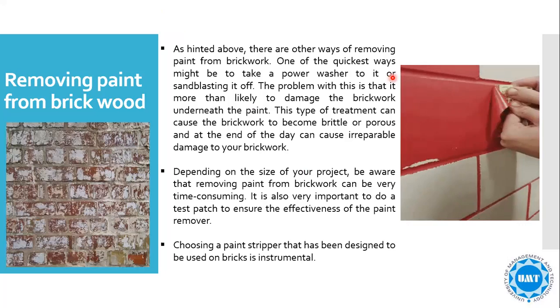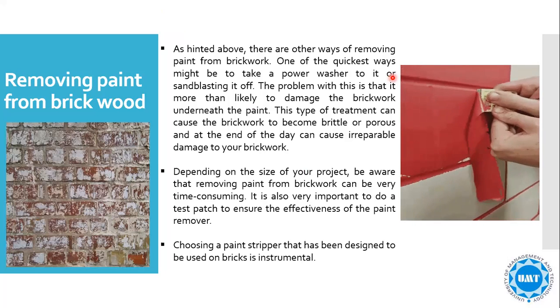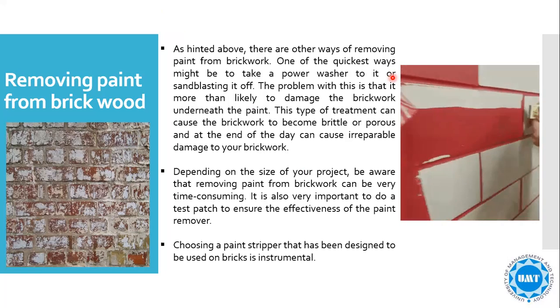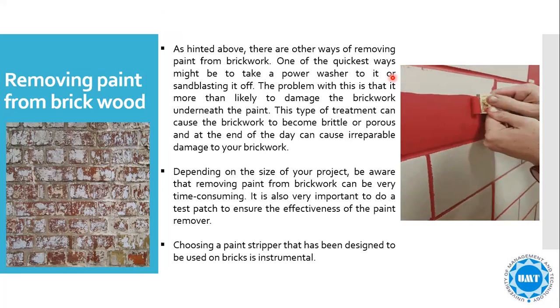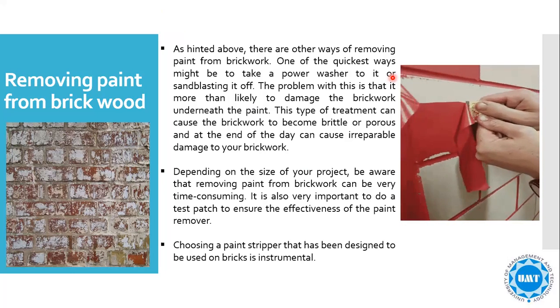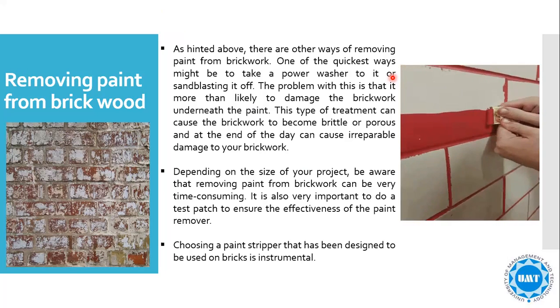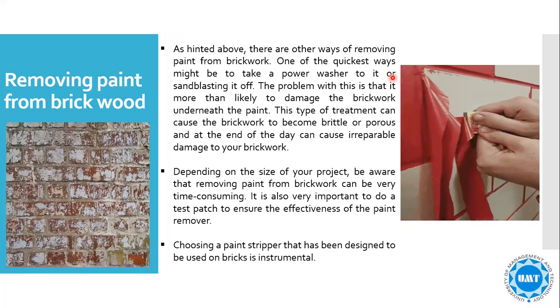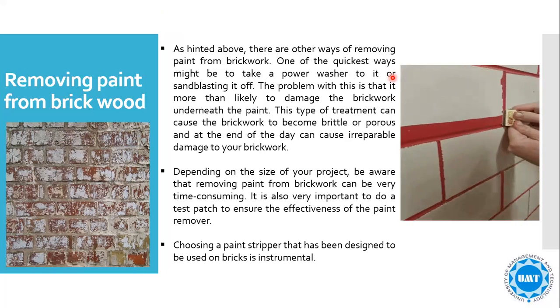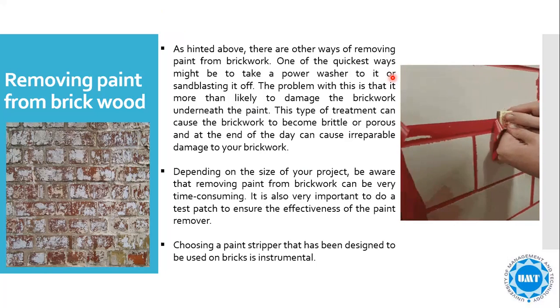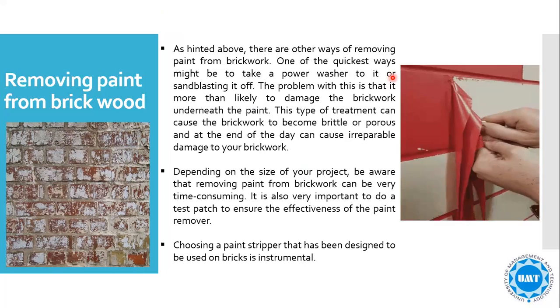If you're going to remove paint from brickwork, as hinted above, there are ways of removing paint from brickwork. One of the quickest ways might be to take a power washer or sandblast it off. The problem is that it is more likely to damage the brickwork underneath the paint.